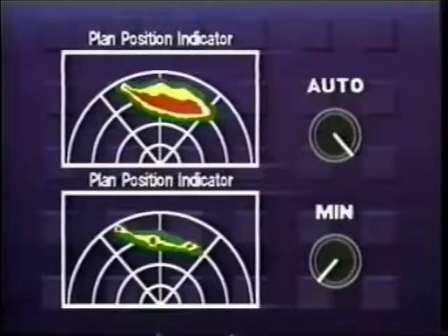Manual gain control is used to adjust the sensitivity of the radar's receiver. One application is to reduce the signal strength of strong target echoes so that they may be resolved on the display. By doing so, it becomes possible to determine the relative intensity differences between strong thunderstorms. As the gain control is rotated counterclockwise, the receiver's sensitivity is decreased.